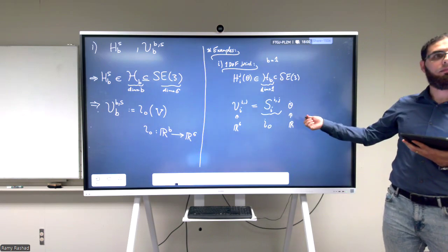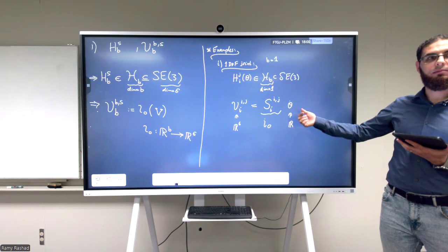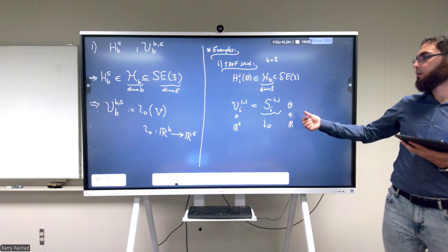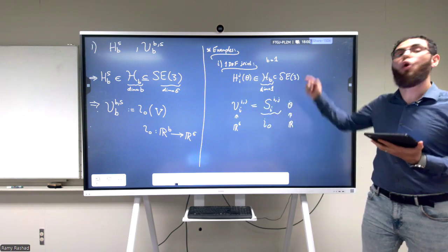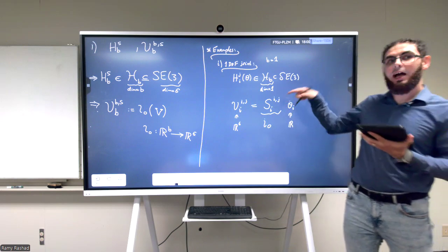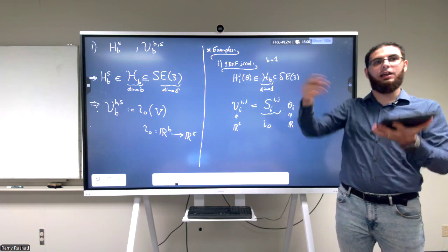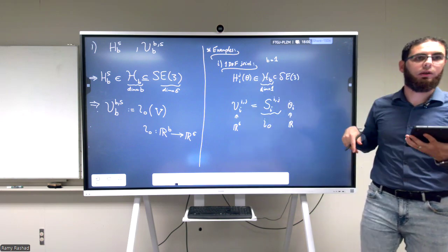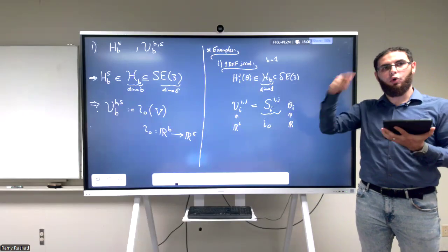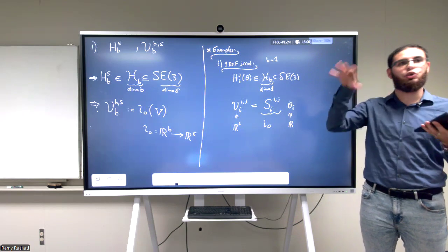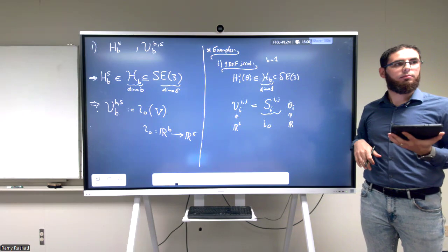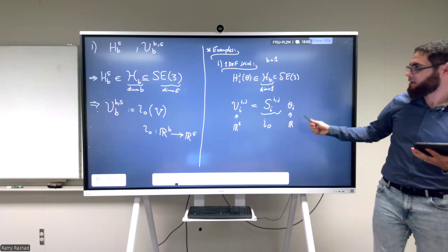Theta dot. The first time you see this? The Jacobian relates it to all of the thetas. Here, this is only theta I. Inside of the Jacobian, if we go back to lecture 12, we're going to find that inside was S, all of the S's plus each other and transformed with some adjoints and so on. So in the end, the Jacobian is nothing else than S's being next to each other. So this is the map here.